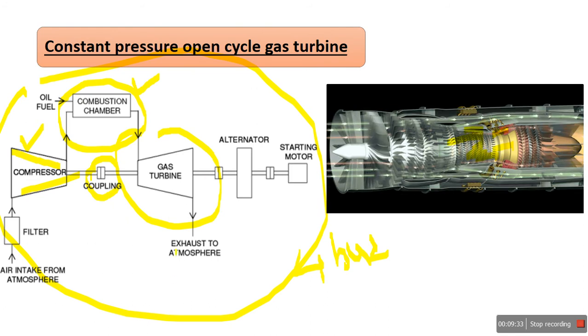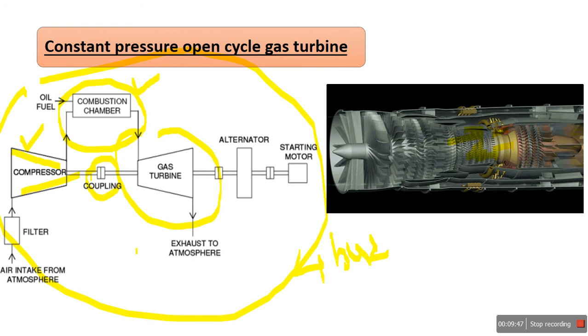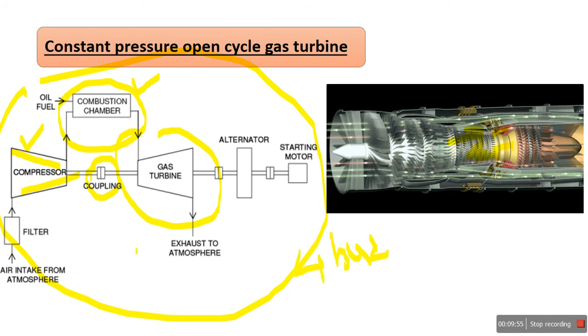Okay, in the IC engine also there is a very important term. For starting, we use the Bendix drive mechanism to start the vehicle. If you start the car with the key, there is a starting motor initially. That is the Bendix drive mechanism, which rotates the flywheel until the exhaust stroke happens. Once the expansion stroke starts, the engine rotates on its own. There's no need of an external prime mover. Then the Bendix drive motor is cut off and the IC engine runs self-propelled.